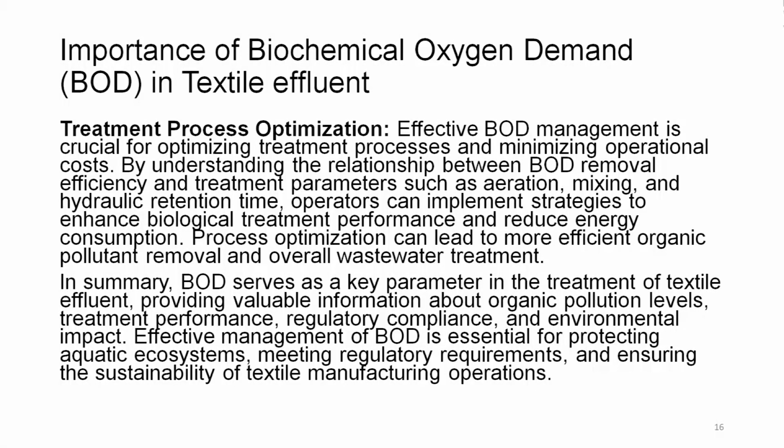Treatment process optimization. Effective BOD management is crucial for optimizing treatment processes and minimizing operational costs. By understanding the relationship between BOD removal efficiency and treatment parameters such as aeration, mixing and hydraulic retention time, operators can implement strategies to enhance biological treatment performance and reduce energy consumption.